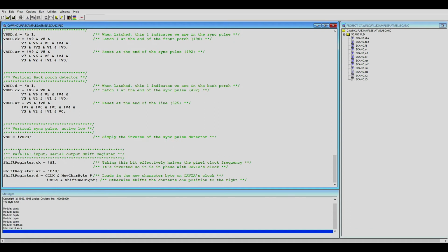The final thing is the shift register, and here I'm using those field declarations, which save space. Instead of writing this 8 times for each one of the bits, I'm writing it for that field declaration called shift register, and the effect is to apply this logical equation here for each of the 8 bits. So what this basically is saying is the following.